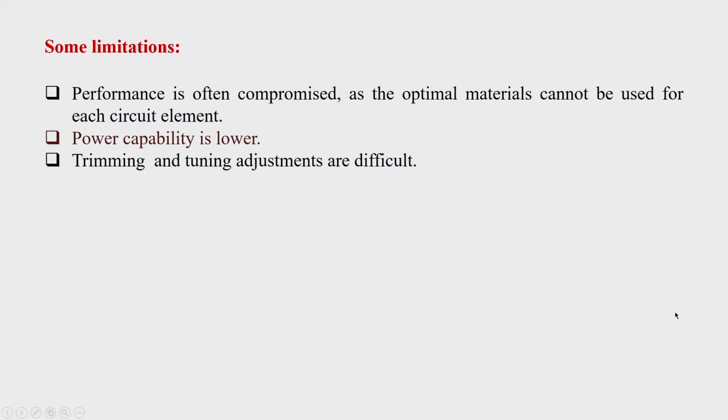Trimming and tuning adjustments are difficult. In hybrid MIC, to optimize the functionality, some of the component parameters can be trimmed, but in MMIC that flexibility is not there, and it is extremely difficult to do any fine tuning or trimming.